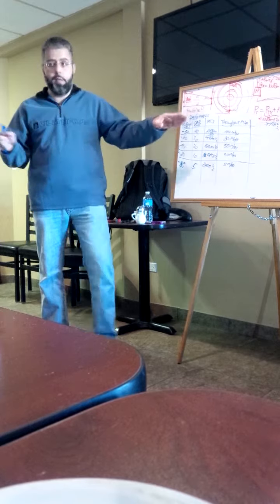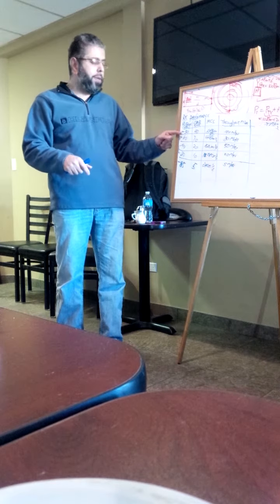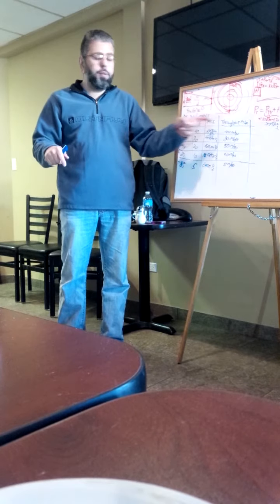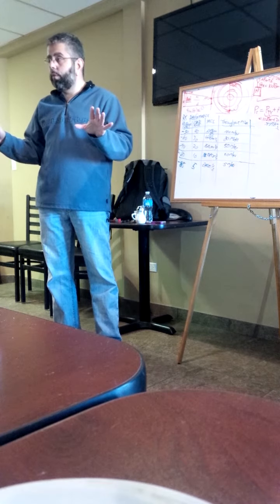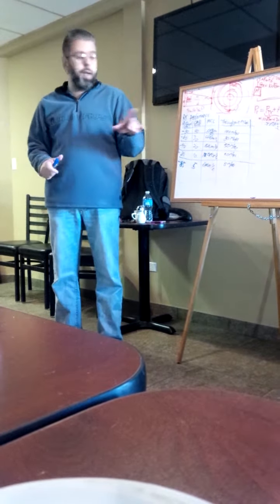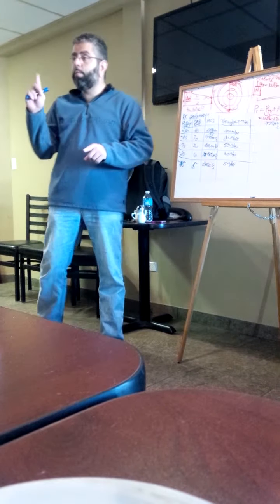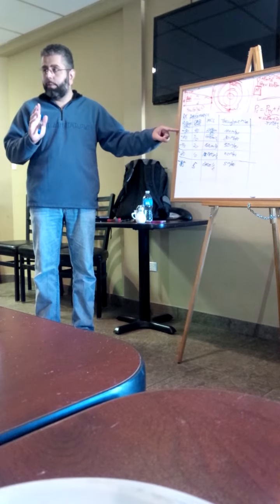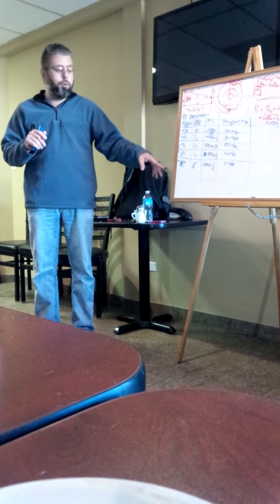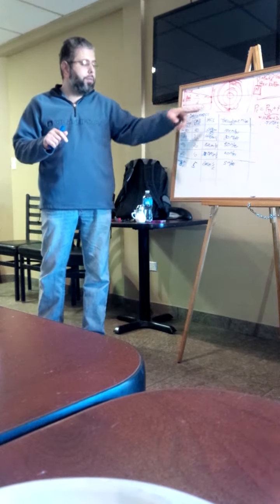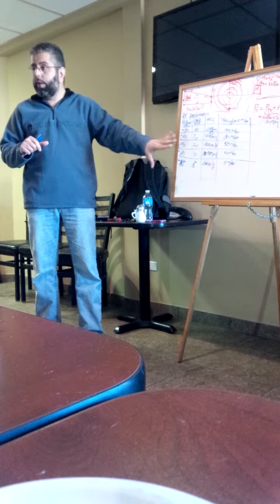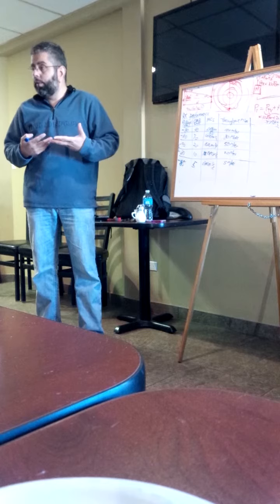So if all of your devices were at minus 50 dBm or higher, and there was no interference in the area, you should be able to share 100 megabits throughout the network. Any one of those devices should be able to do 100 megabits per second all by himself, if he's at above minus 50, for example. This is the table you would ask them for. Give me your RSSI versus throughput and MCS and center. Tell me what those should be. And they would give you this table. Or you pull it out of their spec sheets and find this out.